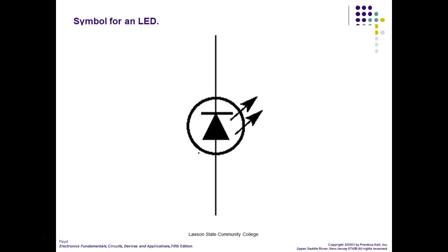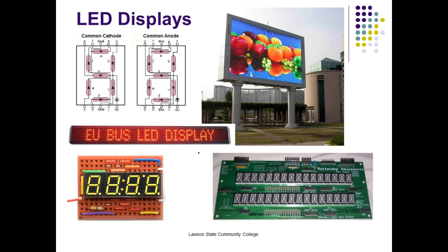If you exceed the breakover voltages, we burn them up. If you exceed the current flow through them, they're going to burn up, right? You understand? So normally we're going to protect these guys with a resistor. But we'll learn later on when we get into transistors, we can come up with what we call current sources, which basically would give a certain current, and you won't see resistors in those circuits. We run into these guys all over the place.